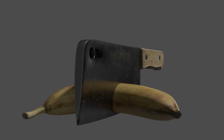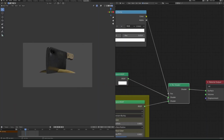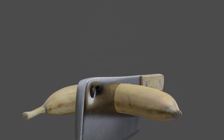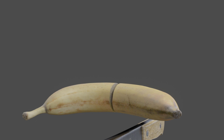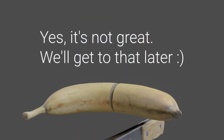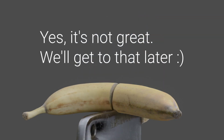If your object is appearing instead of disappearing as the knife moves through it, then you'll want to swap the basic material and the transparent BSDF in the mix shader. If you wanted the basic effect, then there you go. But if you want to know how to add a bunch of other stuff, then hang around and I'll show you how to make this a bit better.